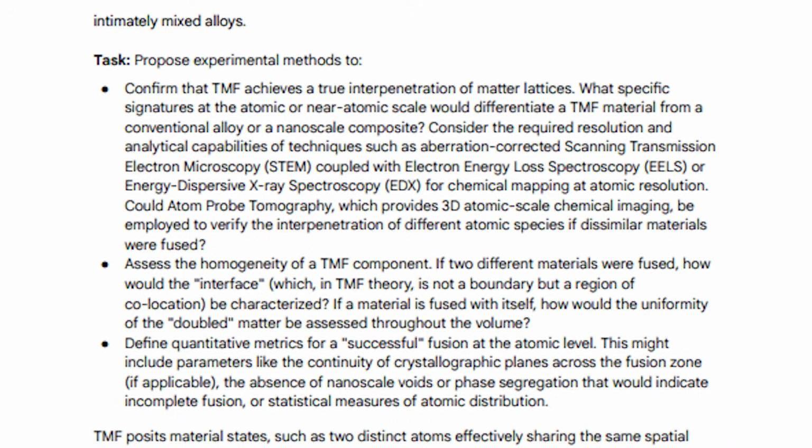Task. Propose experimental methods to confirm that TMF achieves a true interpenetration of matter lattices. What specific signatures at the atomic or near atomic scale would differentiate a TMF material from a conventional alloy or a nanoscale composite? Consider the required resolution and analytical capabilities of techniques such as aberration-corrected scanning transmission electron microscopy, STEM, coupled with electron energy loss spectroscopy, EELS, or energy dispersive X-ray spectroscopy, or chemical mapping at atomic resolution.